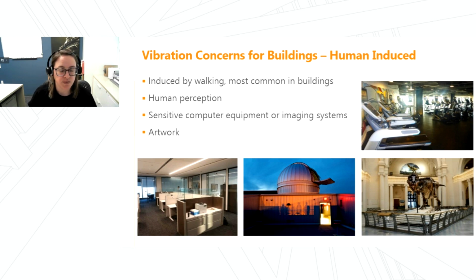The second way that these vibration concerns show up in building is for sensitive equipment and medical labs. Often the equipment in these areas have very high tolerances for floor vibrations to allow the equipment to stay calibrated. The floor framing needs to be stiff enough to limit the vibrations to acceptable levels. In adaptive reuse projects, this is often not the case, and the framing ends up being too flexible and needs to be stiffened. And the last way that we see vibrations in buildings is with artwork.